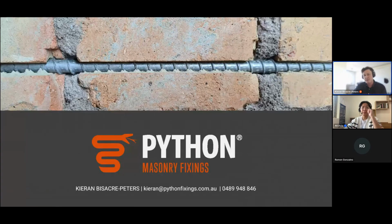Cool. So yeah, really depends on the application, whether you're going to be doing engineering calculations on that, or whether you're reverting to AS 3700, for example, for replacement of wall ties. If you're not relying on composite action, AS 3700 spacings are perfectly applicable. If you're doing something a little bit more detailed, like what you're alluding to, Zurich, you'd probably just run some numbers and ascertain what spacings you need based on the design capacities that we could provide you with for our Python anchors, for example. Hope that answers your question, Zurich. And then if not, feel free to reach out to Kieran directly after this.